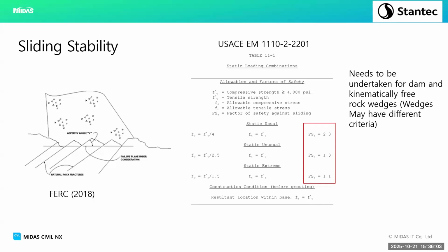Is your jointing, your joint orientation in 3 dimensions, how well it was constructed. You can see, for example, there, the disparities that you have. Under low normal stresses, it would have to ride those ridges to fail in shear. Under high normal stresses, you'd have to shear through that entire rock portion. Again, that's only because those joints are orientated as they are. You need to know your joint orientation.